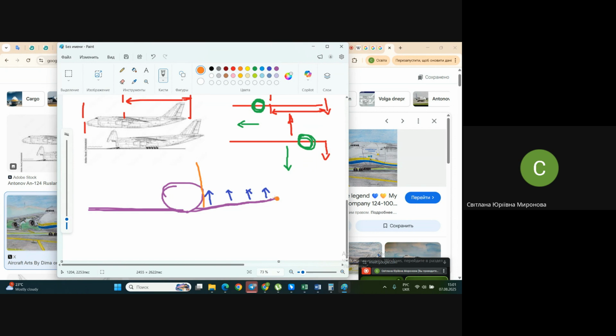And the more distance to this place, the more bending moment at this place. And of course, that is the reason why we have this geometry changing, like the root is longer and the tip is shorter, usually. Because at the root we need a more massive inner structure to resist the bending moment. Okay, but that is the bending moment for a wing that is not loaded with an engine.